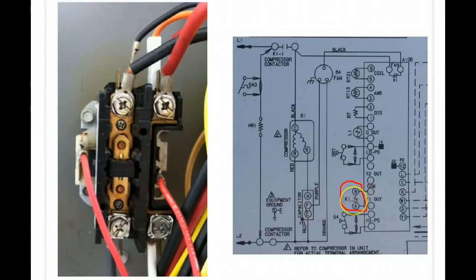So here's our coil. Now what about the contact parts? Well, that's represented over here. As you can see, that's a normally open contact, and it does say compressor contact. So this symbol up here represents this part of the contactor.